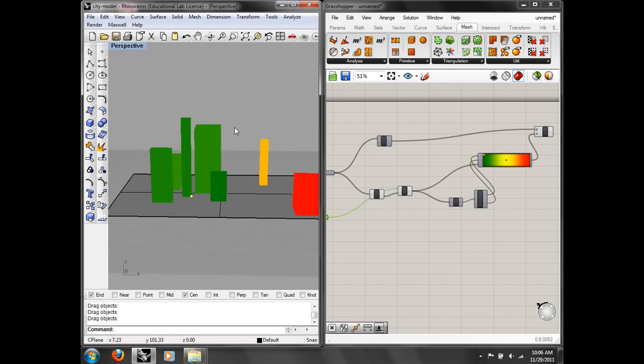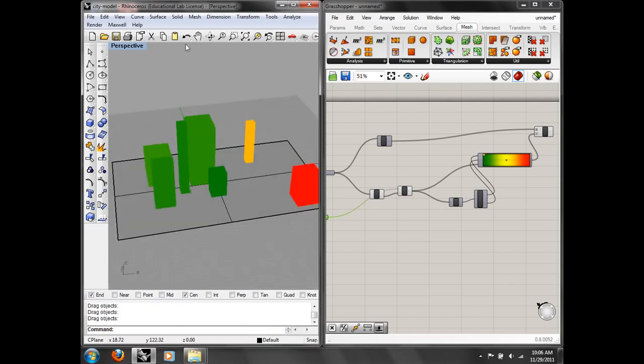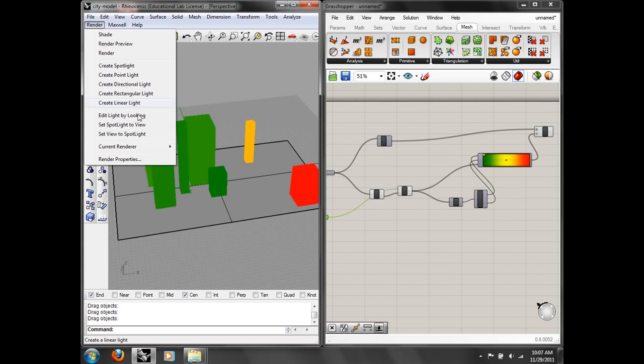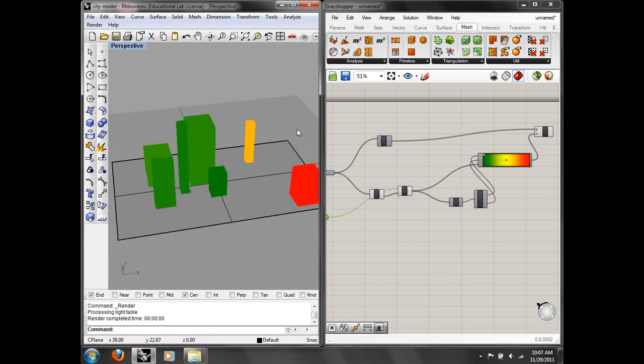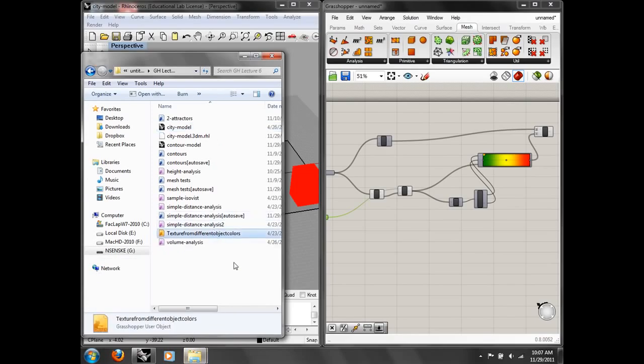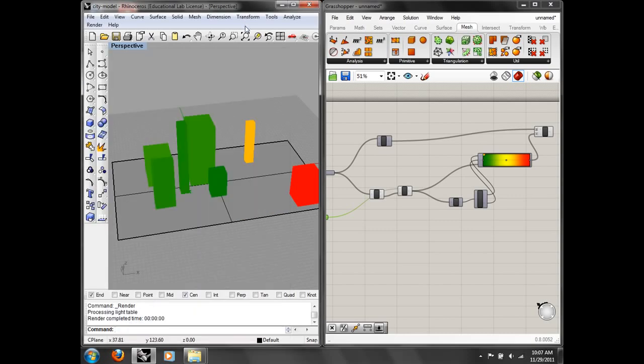To get it out, I will post a component. You can't render this, at least not right now. Maybe in a future version of Rhinoceros. Well, you can't render anything until you bake it. But if you bake this, you don't get the color right now. There's a component that I would give you that basically transfers the mesh stuff to a texture and then automatically applies it. You can't get it out without that component. There's no way to do that. So if you did try to do this, you would get stuck at that point.